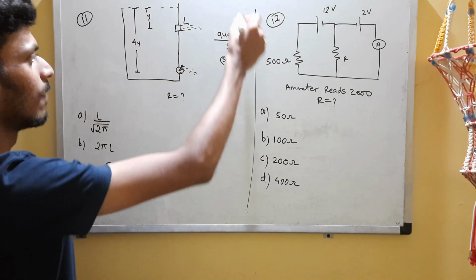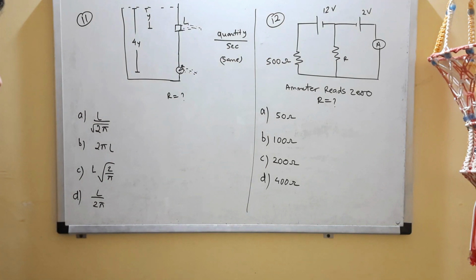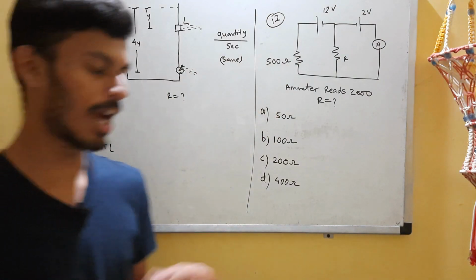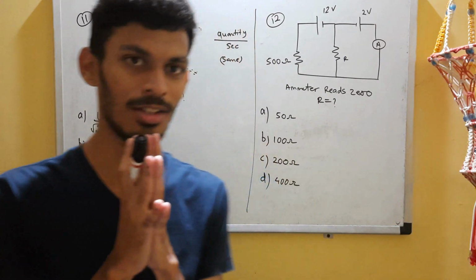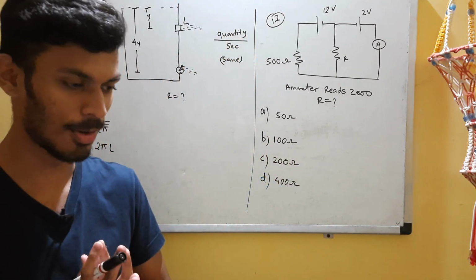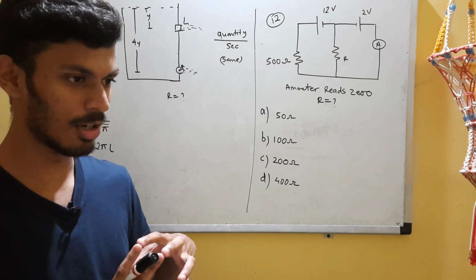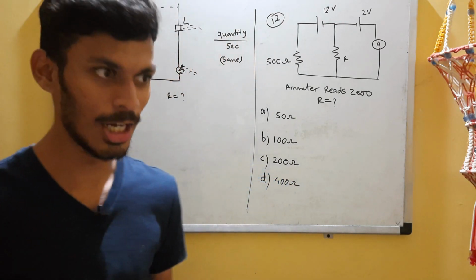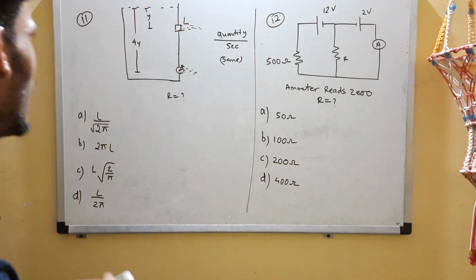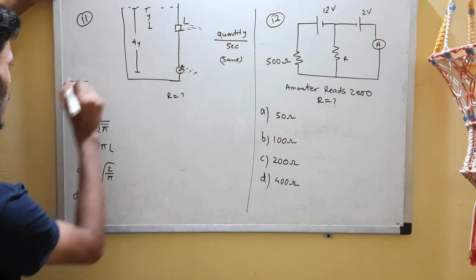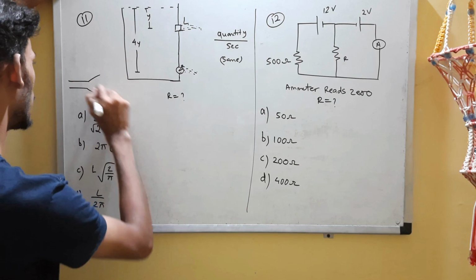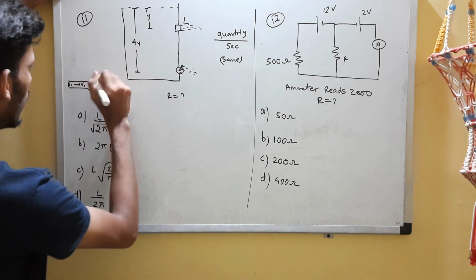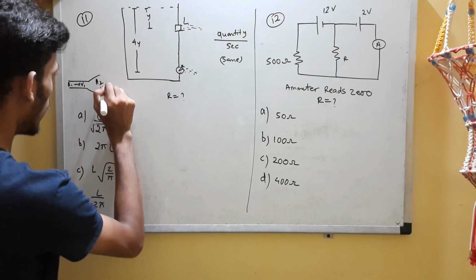First of all, you'll get one clue from here. Quantity per second is the same for both, which means they are speaking of conservation of mass. So the thing you are supposed to apply is the equation of continuity. You might have seen it in simple problems as well: suppose the area over here is A1, velocity of fluid is V1, here the area is A2, what will be V2?